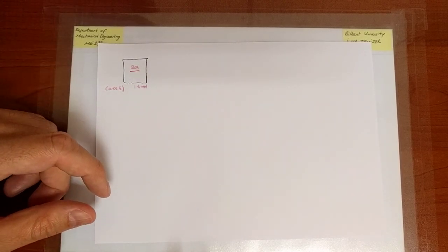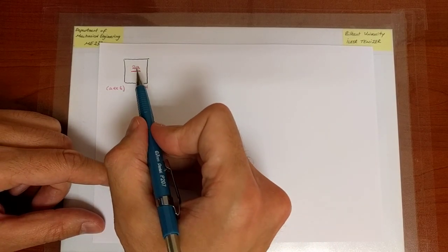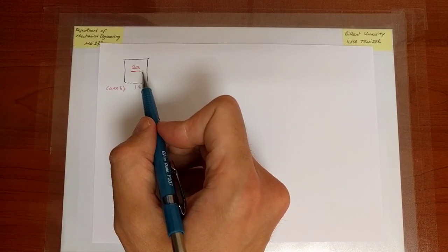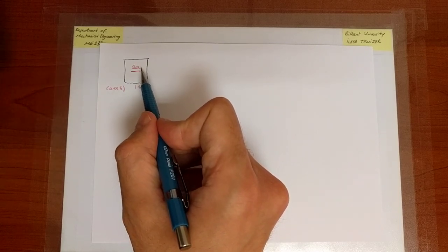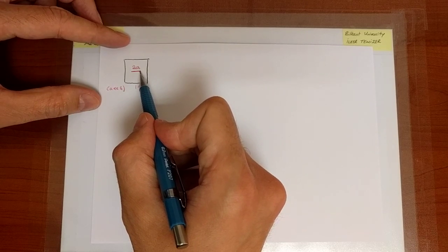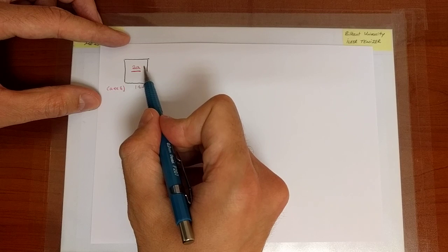Now, what we would like to do is somehow have an explicit mathematical representation of the stress field, including the normal stresses in the y as well as in the x direction. So that's y and that's the x direction, as well as the shear stresses. Not as I move only along the x direction, but along any direction at the tip of the crack.